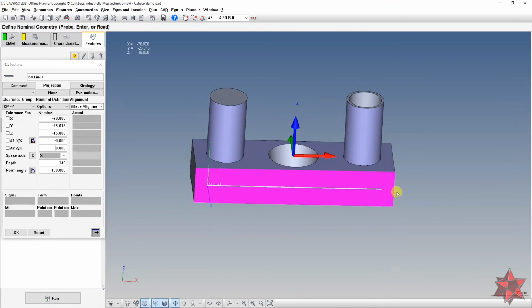So we are safe from the edges and everything. Notice that I calculate everything when I program. If you do it like this, then every part you measure will be measured the same. So keep this in mind: calculate everything, and also work from the closest surface to the closest surface.